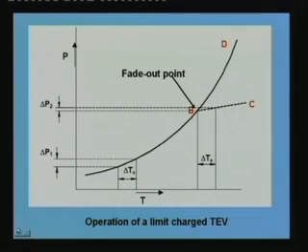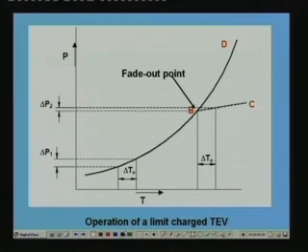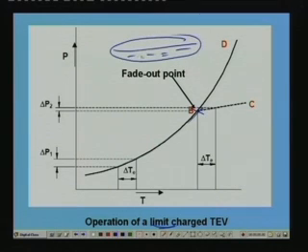So this system is for the limit charge system. Up to this point you have in the bulb, let us say that this is a feeler bulb, you have liquid plus vapor. So as the temperature increases here, this liquid will evaporate, right? And you have charged the liquid in such a manner that at this point all the liquid will evaporate, right?